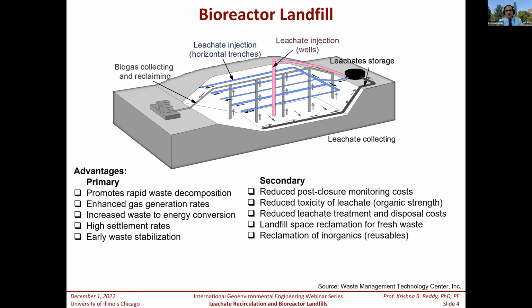In addition to the moisture, you have benefits of higher microbes and nutrients. You will have other benefits that cause higher degradation of the waste. So just simply collecting the leachate, instead of sending it to the treatment, you can re-inject it into the waste and get all this accelerated degradation, and that provides a lot of benefits.